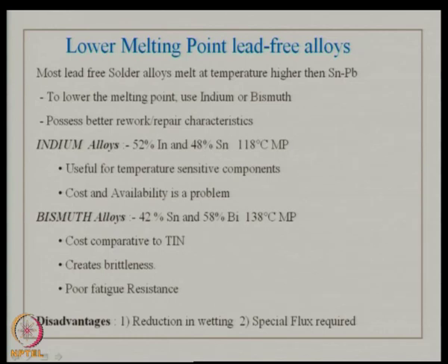Now, lower melting point lead free solder alloys: most of them melt at higher temperatures than tin lead. To lower the melting point, use indium or bismuth, which possess better rework and repair characteristics. For example, if you talk about indium as the component in the tin lead free alloy, tin is 48%.